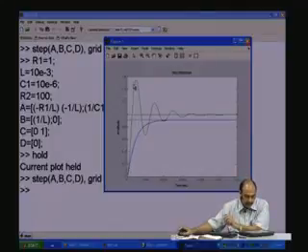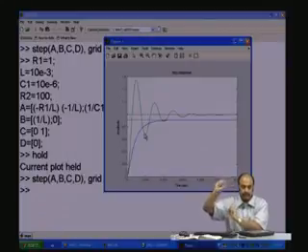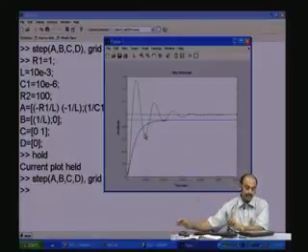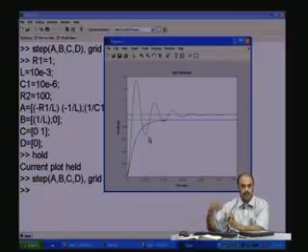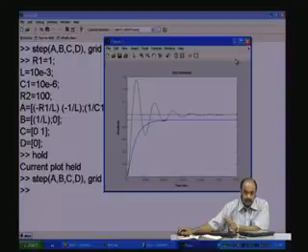And here, because you are getting overshoots, you will see that the 2 poles start moving towards the imaginary axis and they become complex. One is in the upper portion, which is positive, and one is in the lower portion, which is negative. One indicating capacitive effect, one indicating the inductive effect. So, if you have any such oscillation, you should have 2 effects, the capacitive and the inductive effect, which is what we are having in the RLC circuit. This is the interesting point that you will see once you keep varying the parameters.